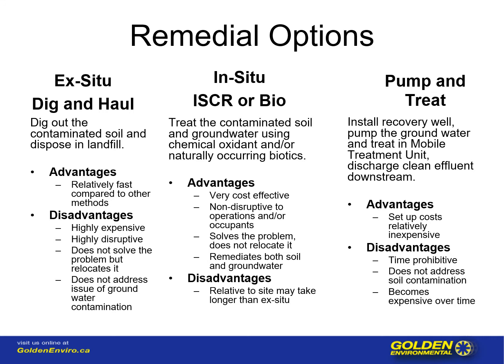We treat the contaminated soil and the groundwater using a chemical oxidant or naturally occurring biotics. The advantage of this process is that it is very cost effective, especially relative to the ex situ and the pump and treat systems.